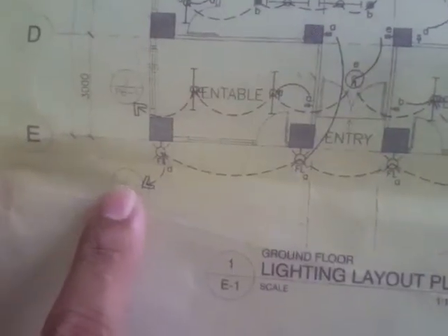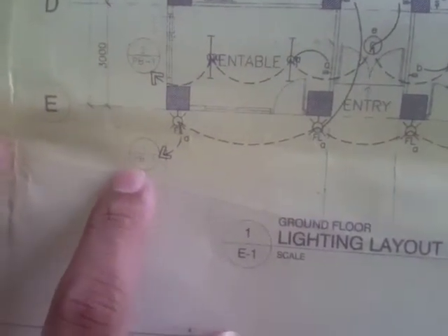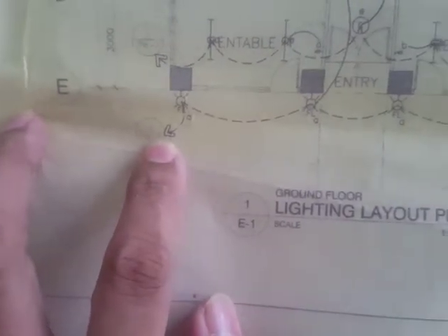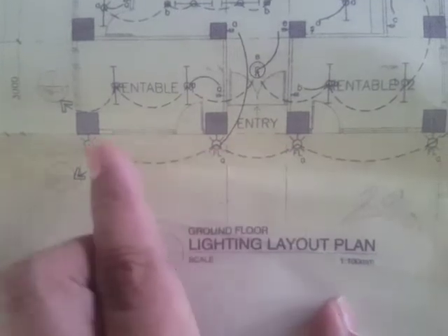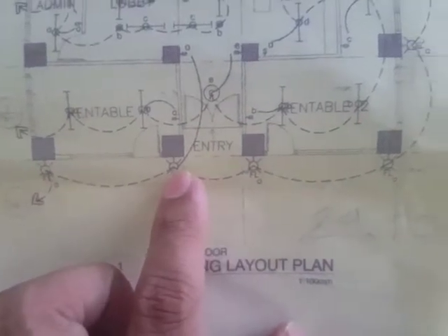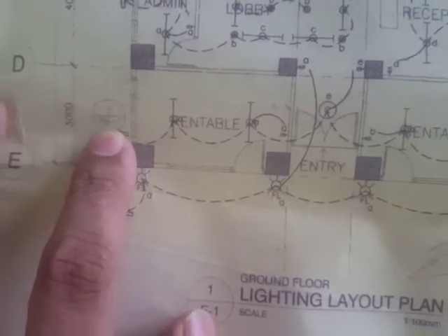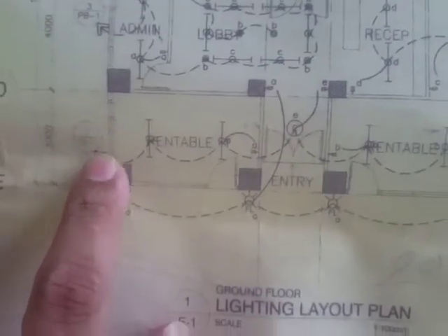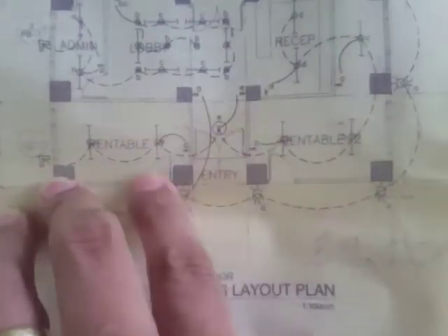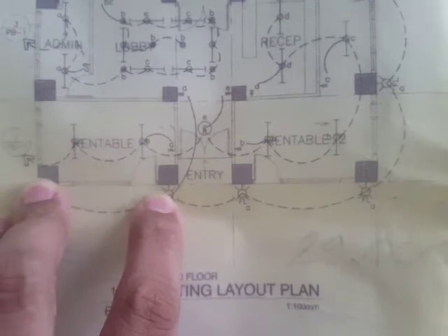Okay, so for example, if you can see here, we have 1 PB-1, meaning panel board dash one, so these lights are connected in one branch circuit. Okay, so another one is 2 PB-1, meaning panel board dash 1. They're connected in one branch circuit as well. Okay, and then this one, I think this should be the location of the switch.